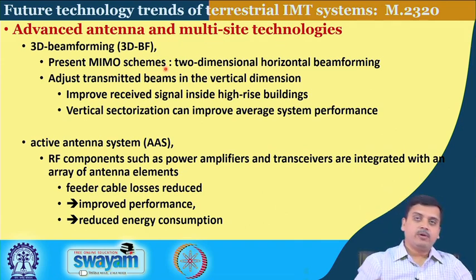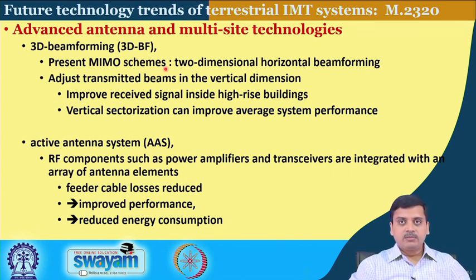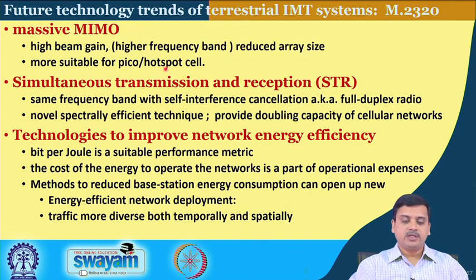Now, with 3D beamforming, what it says is that as there will be high rise buildings, if one can provide 3-dimensional sectors, then there is an even more aggressive spatial reuse of the frequency, which earlier had been restricted to the 2-dimensional plane, whereas now it will be in 3D. With more precise beamforming one could provide better coverage to indoor situations in a dense urban scenario.